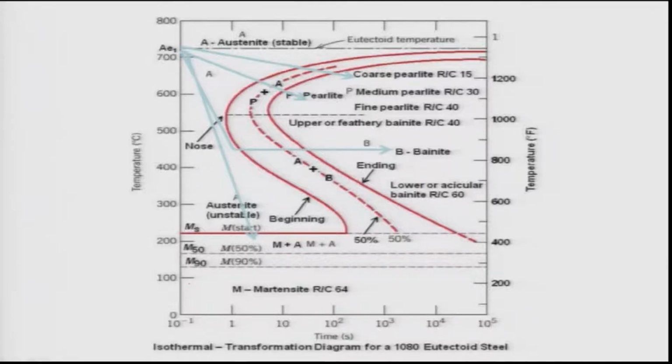Therefore the transformation from austenite to martensite is never complete, because the strain energy, which is a positive part of the energy, will be consuming part of the chemical free energy available for the transformation. Once the strain energy is large enough to take over the whole chemical free energy available, there will be no further transformation possible. That is why martensitic transformation is never complete.